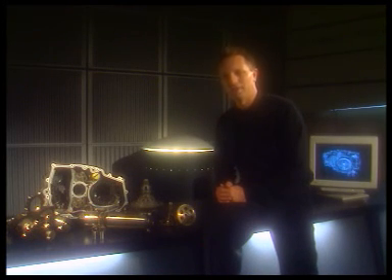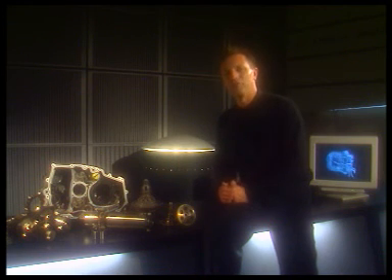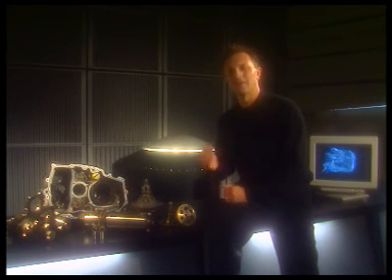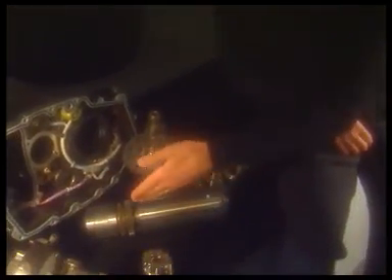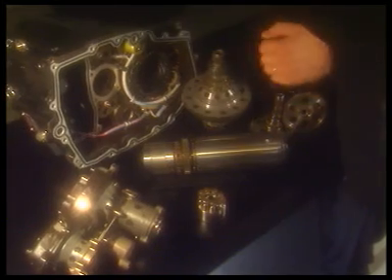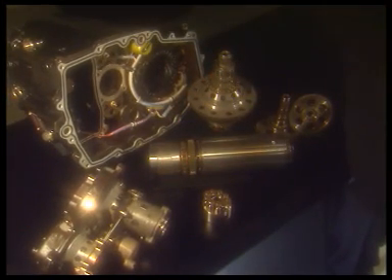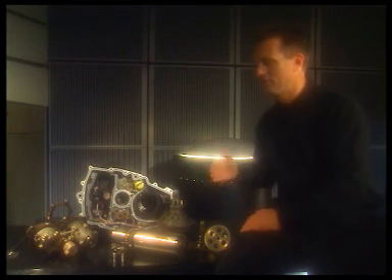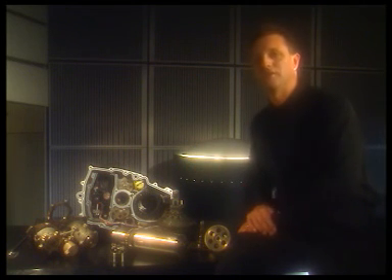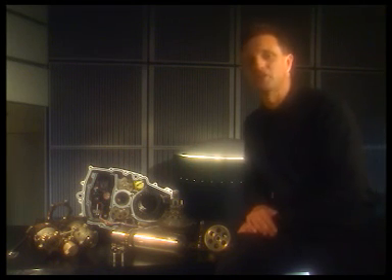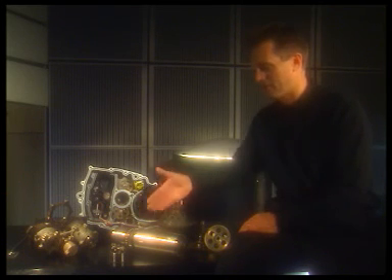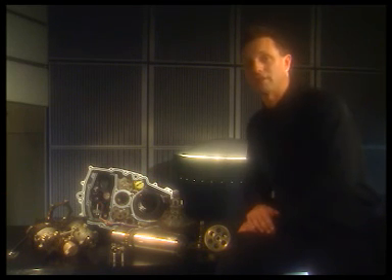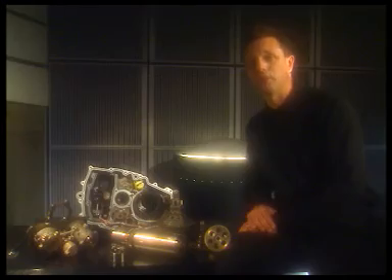The Integrated Drive Generator, IDG, provides electrical power for all the aircraft systems, and therefore its reliability is of the utmost importance. It consists of a generator and a constant speed drive, CSD. The CSD converts the variable input speed of the engine into a fixed rotation speed for the generator. Thus, the generator is able to provide a fixed frequency for the aircraft electrical network.